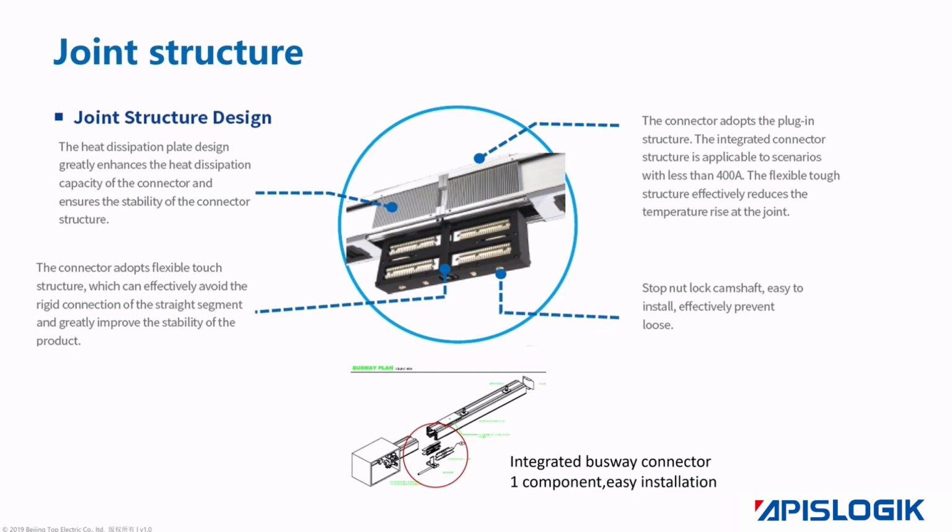The Topline G busbar connector adopts a unified design, and the 160-400A connector can be used universally. The connector adopts an integrated design, low temperature rise, safe and reliable, and the connection principle is the same as that of the tap-off unit. The temperature measurement module is equipped to measure the temperature at the connection. The busbar connector of Topline G is an integral part. Other competing products are generally composed of 2 to 4 parts, and the installation is reliable without special tools, which can ensure the installation is in position.